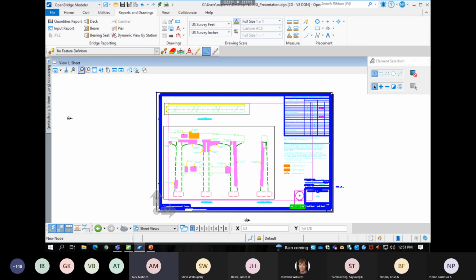And I'll correct myself, as Steve is correcting me, it's only the footing yet, and we're trying to increase that. But again, if you change the analytical rebar, it's not going to update the Pro Concrete one automatically. It just creates the entities, but it doesn't connect them to each other.